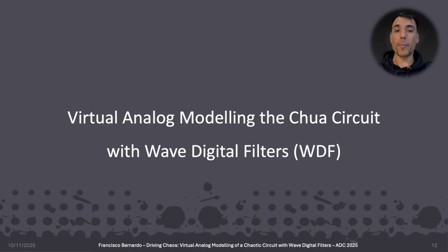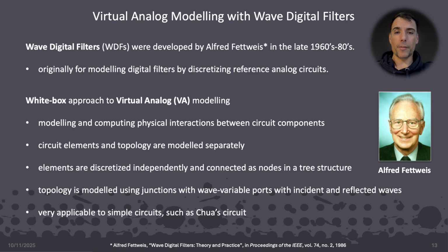A good thing about the Chua system having a piecewise current-voltage relationship is that it can be solved in the wave domain. So we can take advantage of this and implement it with wave digital filters. WDFs were developed by Alfred Fettweis between the late 1960s and the 80s, originally for modeling digital filters by discretizing reference analog circuits.